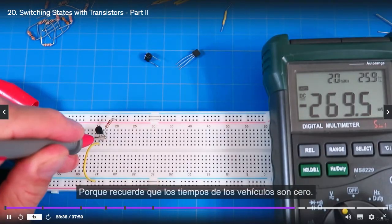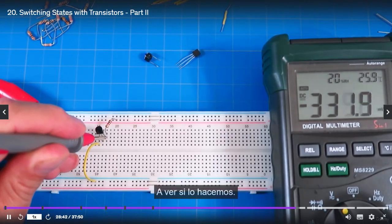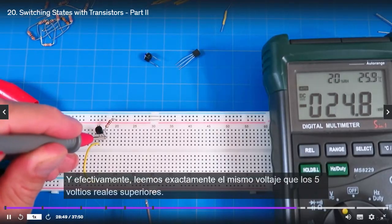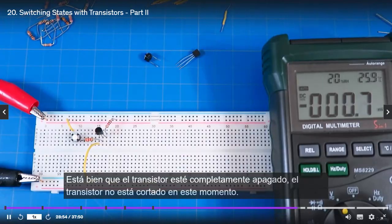Because remember, V equals I times R. If I is 0, then there's no voltage drop. So we should read 5 volts right here. Let's see if we do. And sure enough, we read the exact same voltage as the top rail, 5 volts. Okay, the transistor is completely off. The transistor is in cutoff right now.